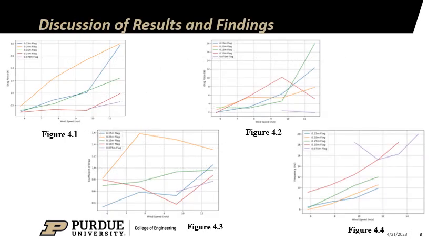The first aspect that the team wanted to observe from the test was how the effective drag coefficients of the flags would compare to the skin friction drag of a flat plate of equal size. In our proposal, we predicted that due to the kinematics of the deforming flags, the drag coefficients would be significantly higher compared to that of a flat plate. From our results, we found that this prediction was true, and in figure 4.3, we see that the flags had a drag coefficient that ranged anywhere from 0.3 to 1.6, compared to those of the theoretical flat plate, which we calculated to be 0.07.